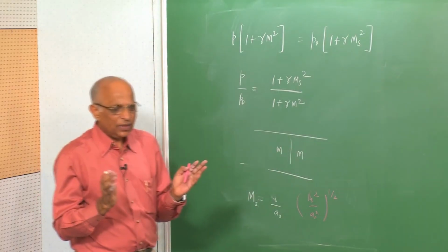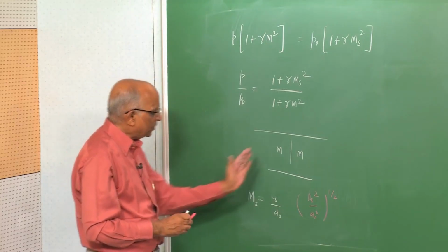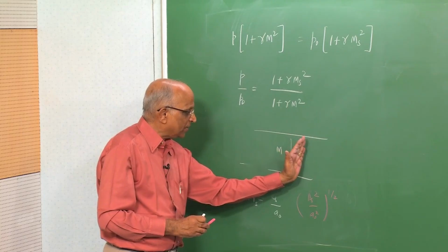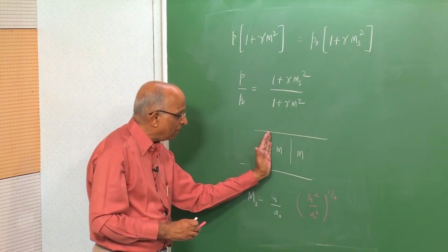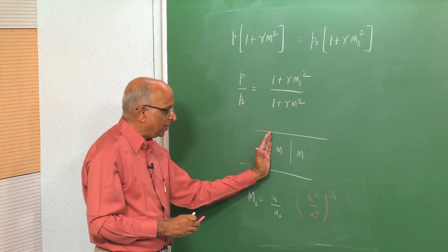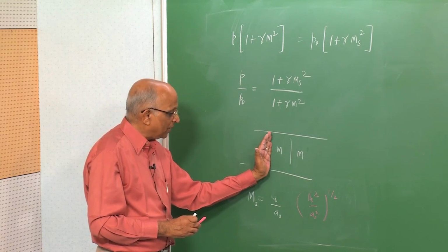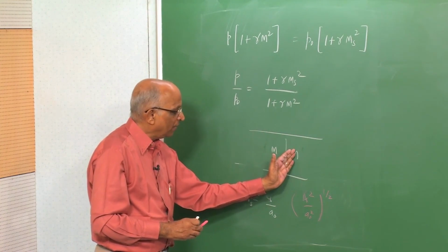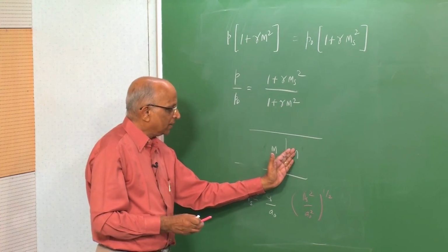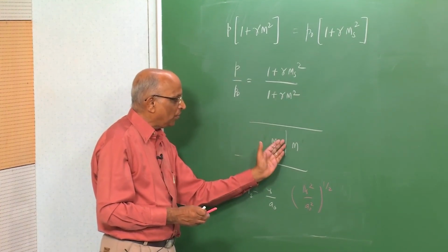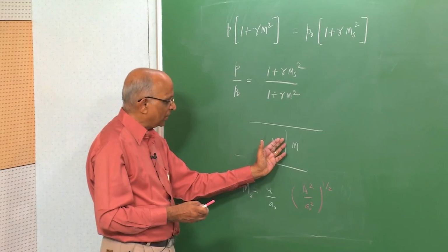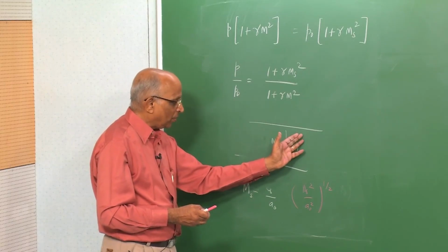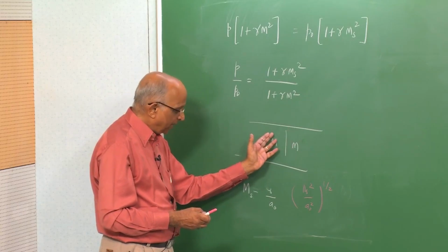Therefore, to summarize, in this particular class, we started with the discontinuity moving. We looked at the properties ahead of the shock and behind the shock, and we got an expression, namely the shock Hugoniot, which linked the properties. Then we said that the shock moves at a particular velocity, which was defined by the Rayleigh line. The intersection of the Rayleigh line with the shock Hugoniot or the Rankine-Hugoniot relations gave you the properties, namely pressure and density dependence with respect to ahead and behind the shock.